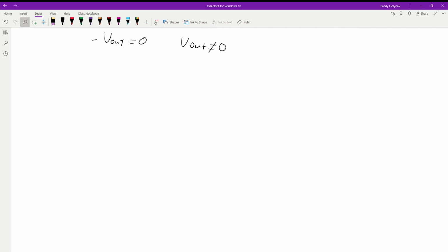So first thing I want to start in with is superposition. Basically the steps we have for superposition is we want to identify our voltage sources. We want to solve each supply individually by shorting out all the remaining sources. So when we do one, we're going to short everything else out. When we solve the next one, we'll short everything out according to that.